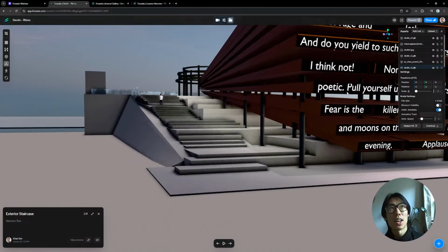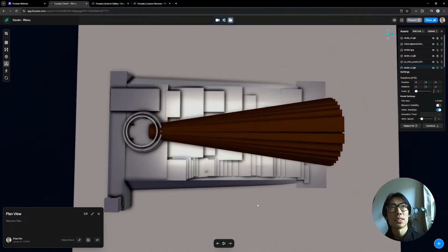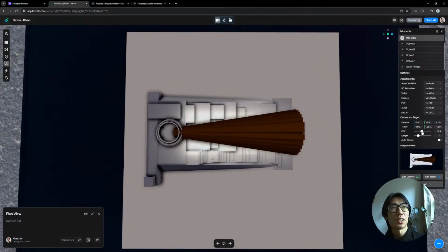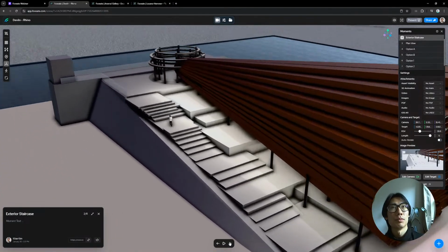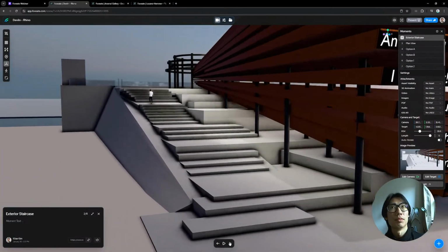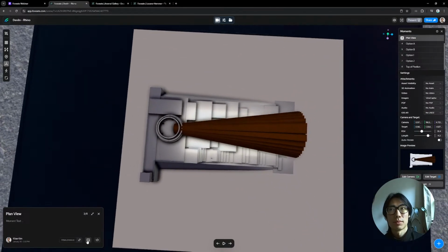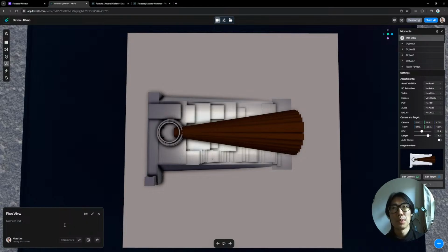So yeah, Foveate will automatically tween between all of your moments as soon as you press the arrow keys. So let's say you want to change the FOV at this particular moment and the time it takes to get there, Foveate will automatically recalculate that information for you, and it updates this label here. So the assets that you attach per moment, they will change between moments as well.